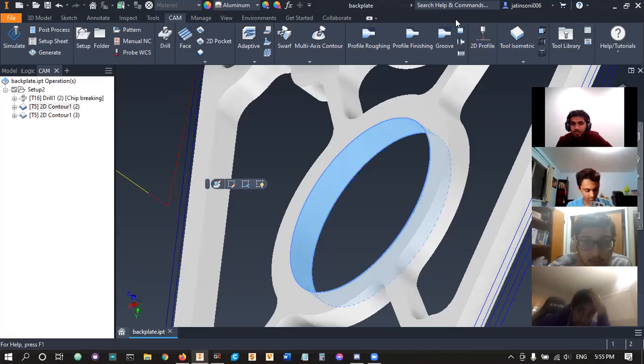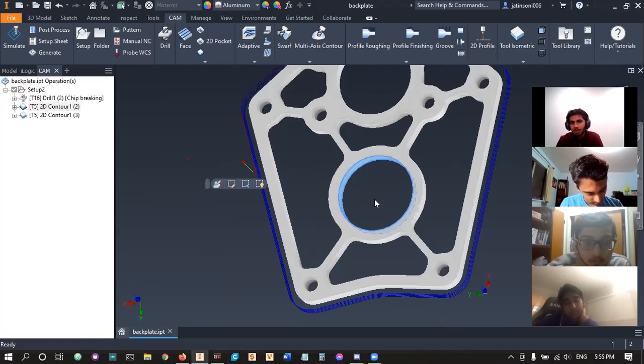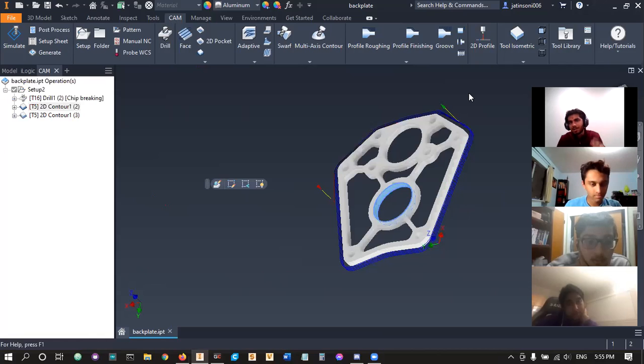So for the lead-in and lead-out, is it only for the contour? You can do it for anything with an end mill, adaptive or contour. But for adaptive, because you start in the middle portion, you don't need the middle of the bearing hole anyway, right? So the lead-in doesn't matter. The lead-out would be useful. For contour, they'll lead in and out because you're cutting the entire shape.